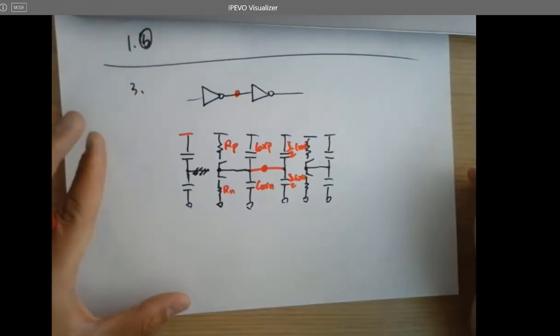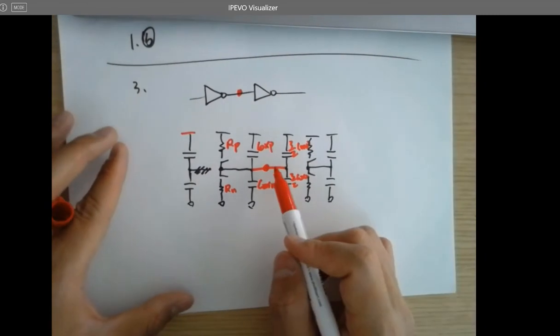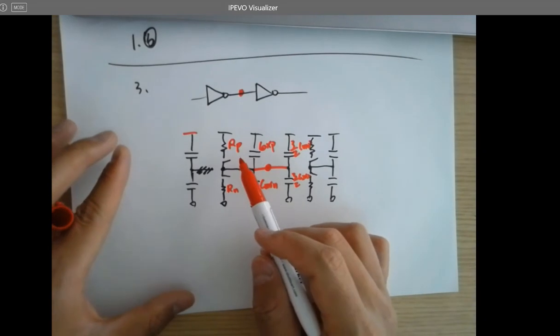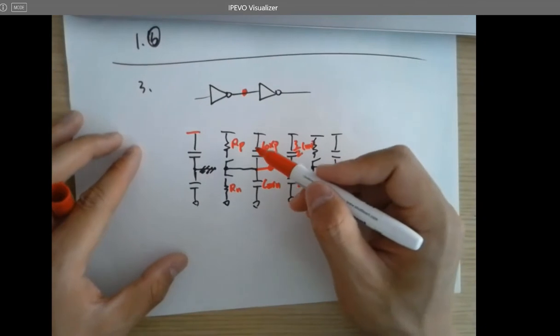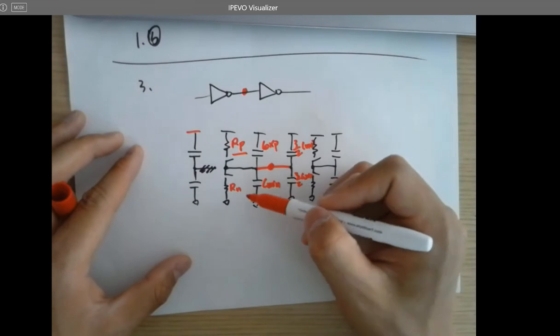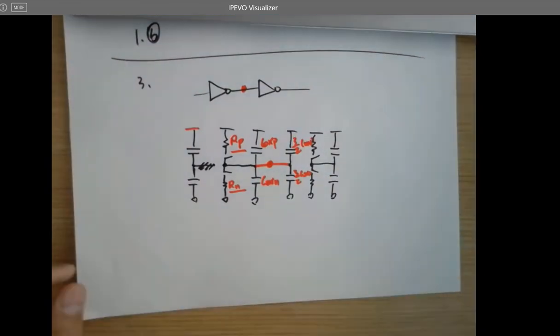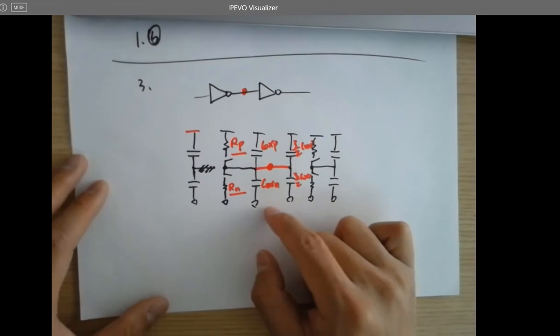Okay, so if you draw the model like this, it's very clear how much capacitance and how much resistance are involved. If you're doing TPLH, you want to use RP. If it's TPHL, you want to use RN. So this is the only thing you need to draw, even in the final exam, right?